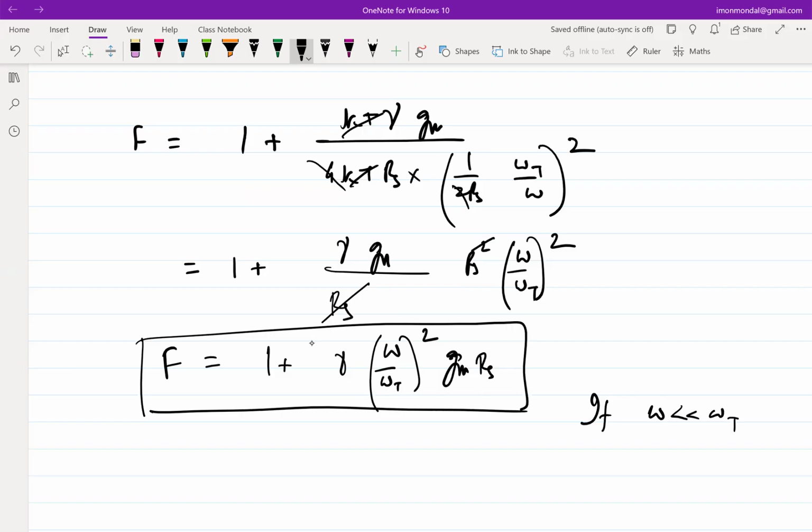The input referred stuff is useful when you want to give it as a model to somebody who is driving your block. For your own analysis, you have to make a call which analysis is simpler. If the input referred doesn't have any correlation, then surely. But in this case, input referred will have a correlation. So that is why we generally tend to not do input referred if possible.